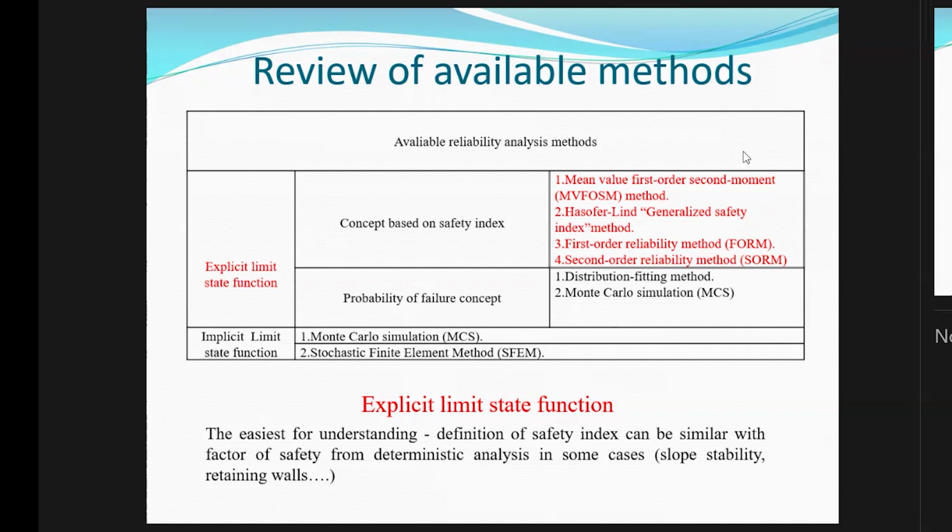But nowadays, even in structural engineering, especially in earthquake engineering, the new design codes like the Eurocodes demand that we design the building to resist a 475-year return period earthquake. So the more we quantify the uncertainties in our inputs, the outputs and the results should be not a single point value, but a probability distribution curve.